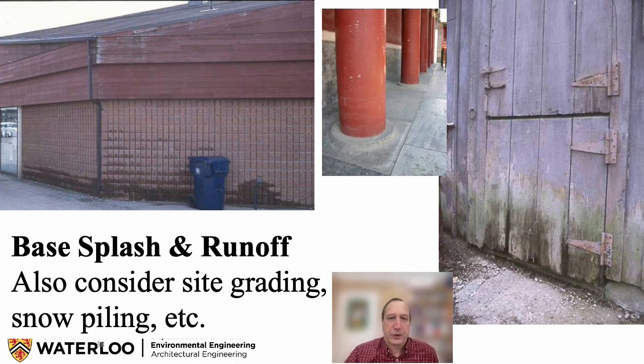Here on the upper left, you can see the University Shops Plaza. We have a pitched roof which dumps water into this eaves trough, but the eaves trough is on quite a steep slope, which means that during heavy rains, the water runs down here, goes past the downspout because of momentum, and jumps over and causes this wood fascia to rot. The response is that they repaint that every 3 to 4 years and then replace the wood every 10 years until they finally have covered it up with vinyl siding over building paper. I'm not sure if that's solving the rot or hiding the rot that's going on behind for a longer period of time.